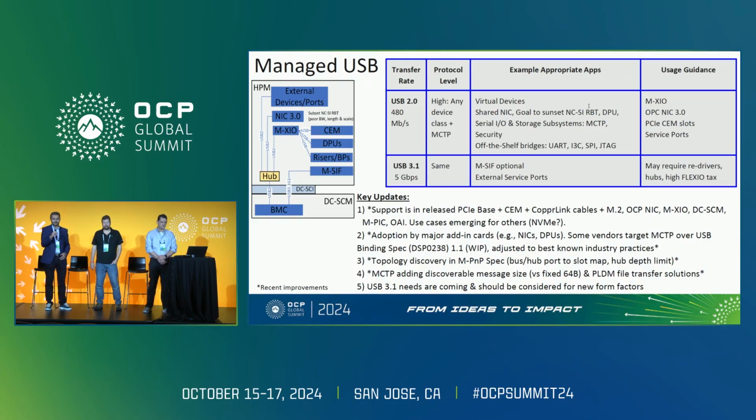It's becoming the out-of-band management interface of choice in many cases. There's a lot of industry goodness already available. All the parts that are providing bridging over USB to all sorts of interfaces like I3C, I2C, GPIO expanders, UARTs. And I3C is also provisioned, as you can see on this diagram, in most of the I/O expansion connectors and modules within the MHS.